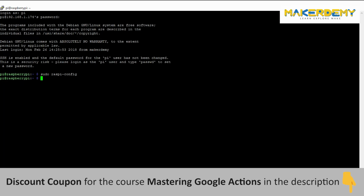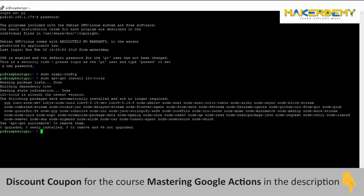The next step is to install the I2C tools that will help us in finding the address of the connected device. Download the I2C tools using the command sudo apt-get install i2c-tools. Finally, you need a Python library to access the connected device from your Python script. Download it using the command sudo apt-get install python-smbus.